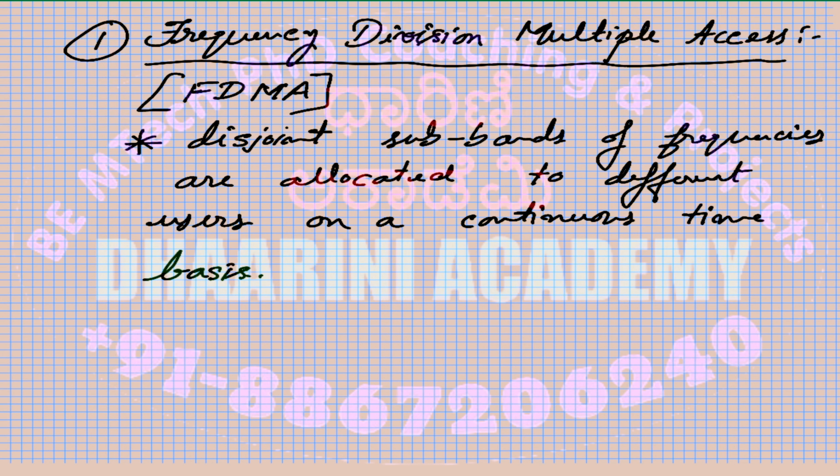Right? So now let us say communication will happen, each user will use their own subband. Whenever it comes to frequency based communication, there will be interference because of some non-linearity in the channel, or on the source side, if your frequencies are not integer multiples of each other, you will see they are not orthogonal, so definitely the concept of interference comes into the picture.